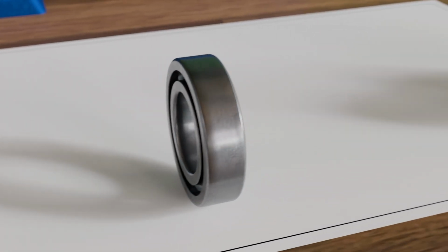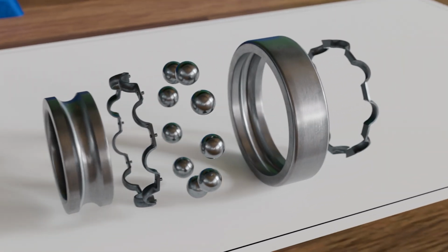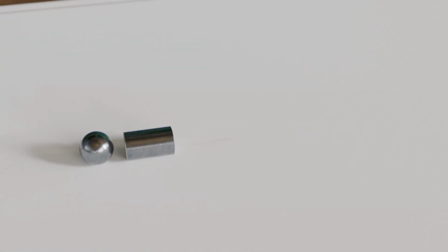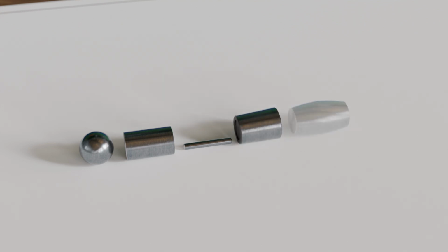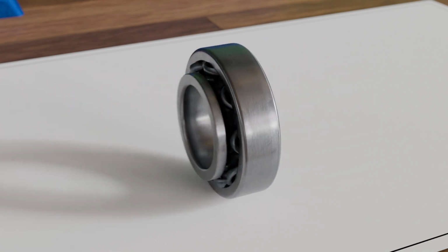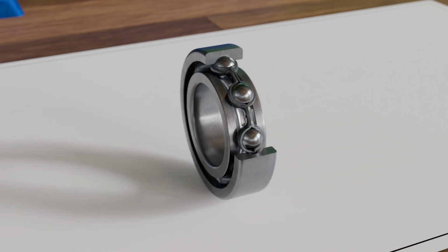In contrast, rolling bearings operate with rolling elements that are positioned between an inner ring and an outer ring. These rolling elements can be small balls, rollers, needles, cones, or barrels. During operation, these elements roll between the rings, largely replacing sliding friction with rolling friction. Since rolling friction is physically much lower than sliding friction, rolling bearings are characterized by low energy loss. They also often require less maintenance. In this video, we will focus primarily on the group of rolling bearings.